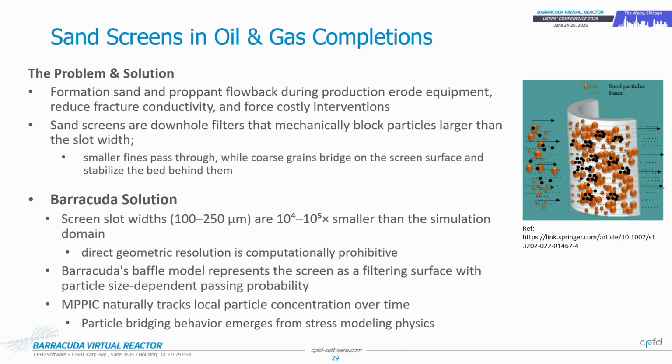As I said, the lengths of these wells can be hundreds of feet. But even on a decent CFD case, if you were to model a 1 meter length section of your sand screen or a 9 meter section, the disparity is quite big. If you're trying to resolve each individual slot in your screen and then still grid all the other domain itself, you're running into millions, if not billions of cells. So quite impractical to do.